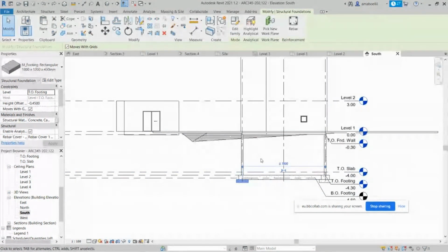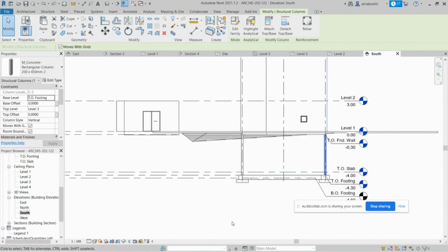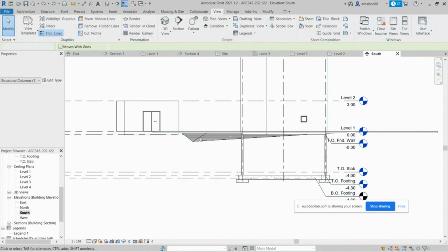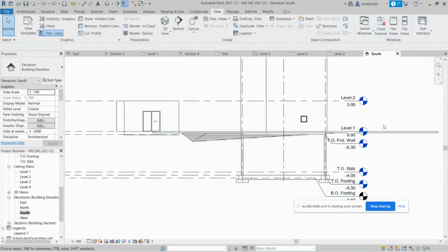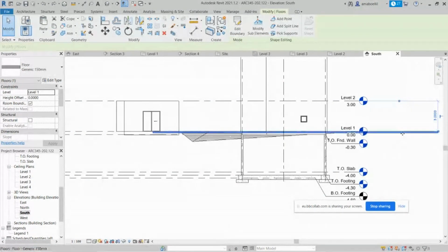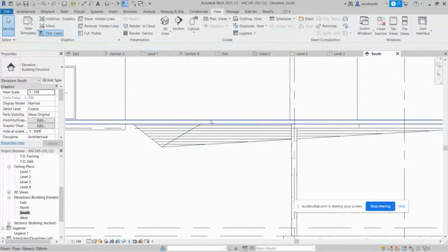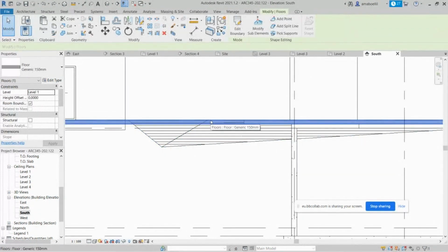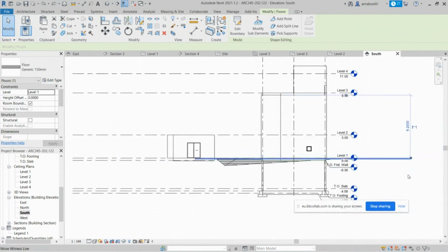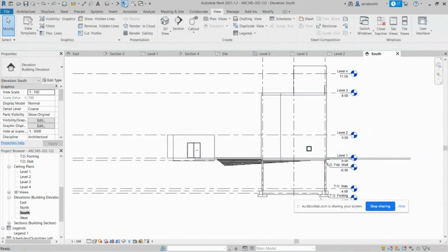And if you want to just delete, mask it, you can still go to masking and do a mask on the top of this, and it will not show any of these elements, so that you can still pick, and you can mask similar to what we have shown before, so that you mask the lower portion to the ground level in here. But you might also pick the lines of the ground level, and if you want to show it, you can pick that line and change its thickness to show it as a thick line, or you can make a region and fill this region with a solid line in order to show the ground level of your plan if it's not shown adequately in the elevation.